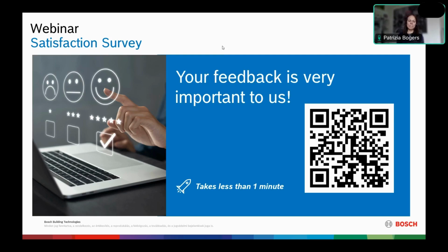What can be done in a situation where there is low visibility, let's say high fog? This is exactly the point that needs to be considered when we have high density of fog in the image. Either the camera triggers due to the fact that the movement of the fog is similar to a real smoke event on which it is trained, or on the other side we can deal with the fact that the field of view is just not covered, meaning the camera cannot see the fire event, and this needs to be closely monitored.